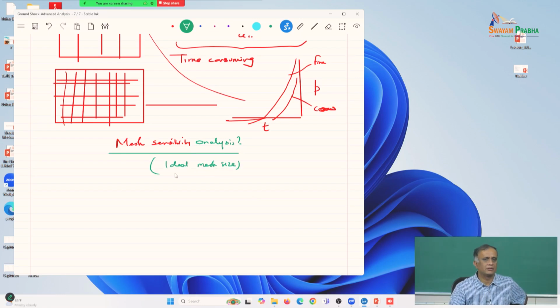Problems with concrete and the mesh size, it depends on many things. It actually depends on even your Lagrangian mesh sizes. Mesh sizes also depend on the type of material used. So I've found, for instance, that for concrete, for the simulations we had, the 1-inch mesh size simulated the experiments best compared to even half an inch.